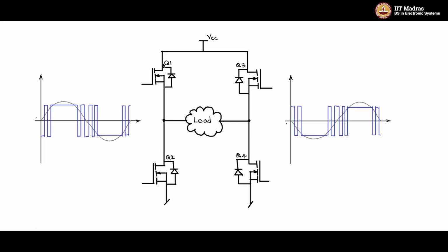So during the transition time, there is a very small period of time where there can be a shoot through, means there is a current that can flow from VCC down to the ground through the Q1, which is transiting through the linear region, Q2, which is again also transiting through the linear region, which means that there are finite conductivities.